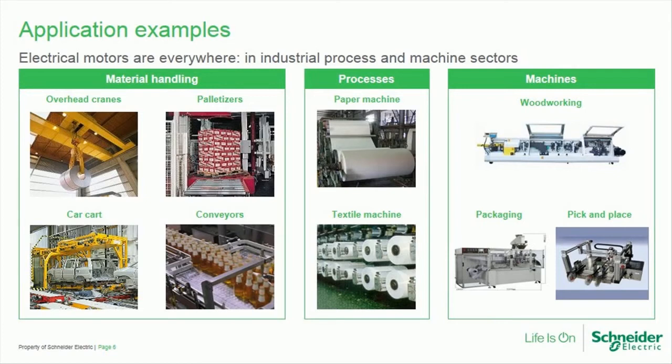Let us take an example of a crane. When the crane is loaded, at the moment start is required, there is a braking function enabling the motor brake to open at the right time to ensure movement will be fluid. This function, braking logic, is embedded and can be managed totally by the drive. This is equivalent to your handbrake management with a car. Several examples can be taken as our drives embed lots of functions for applications.